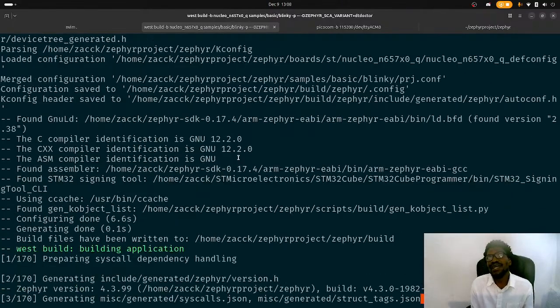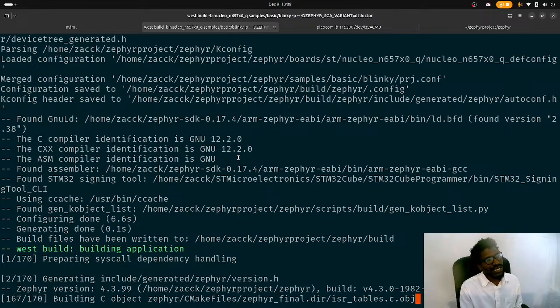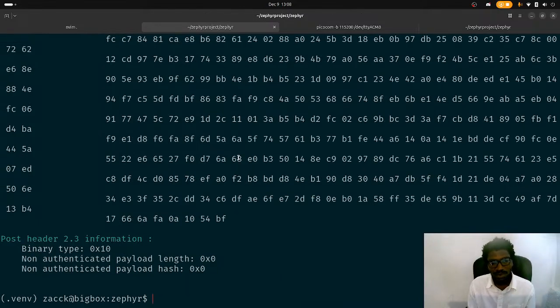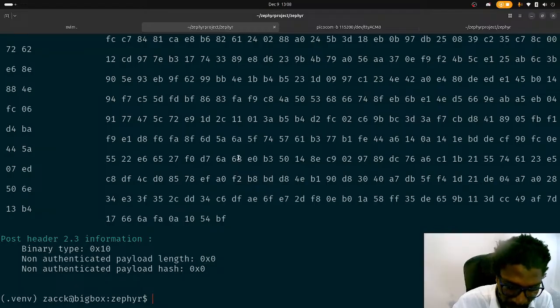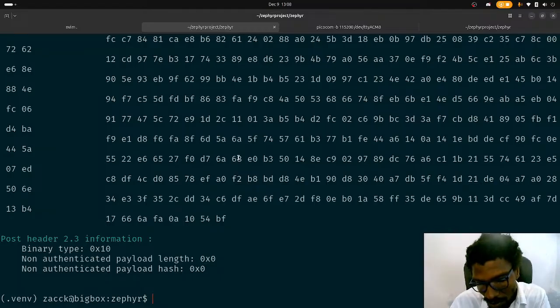Let's see. It's not open drain, because it's not just out. It could be open drain, but I think it's going to be push pull. But it could be open drain because we're turning the power on, the power off, power on, power off. So it's going to either be 1 0 or 1 1. That's basically it. And if it's that way, then I think we're done. We're really set up correctly.